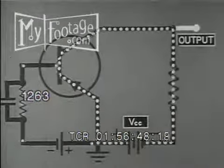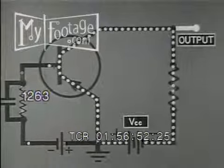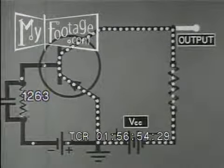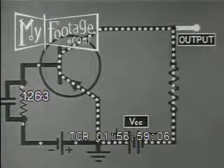This produces a surge of carriers into the base so that enough are available almost immediately to produce maximum collector current. This is a basic switching circuit, a fundamental building block for computers used in many ways to perform mathematical operations.